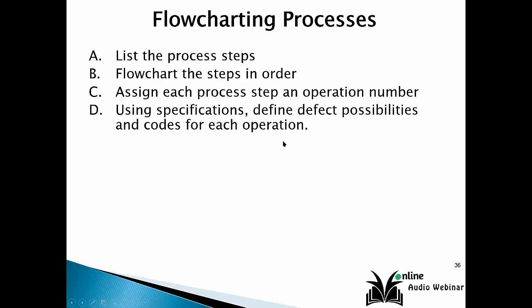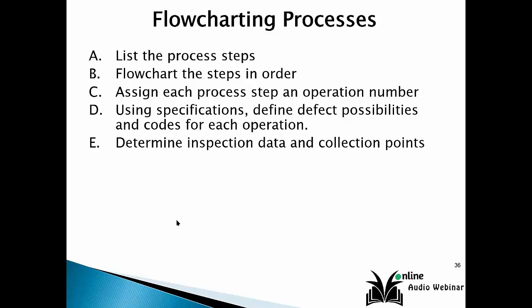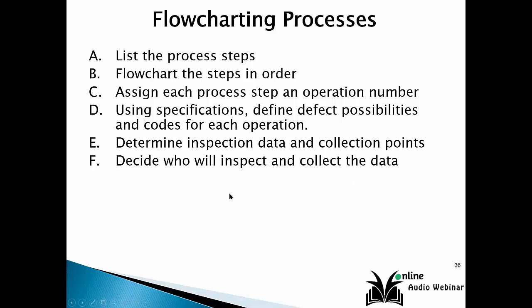Using specifications, define defect possibilities and codes for each operation. Determine inspection data and collection points. Who will inspect and collect the data? Prepare inspection forms and practice inspection and data collection each step.